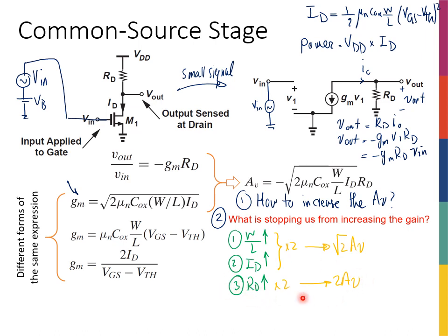So the first thing that we're paying is area, right? If I have a 1 kilo ohm resistance and I make it 2 kilo ohm, it's going to be basically twice as much area, right? But is it that important? Well, definitely an order of magnitude less important, a lot less important, significantly less important than power consumption. So I am a lot more flexible with the area compared to power.